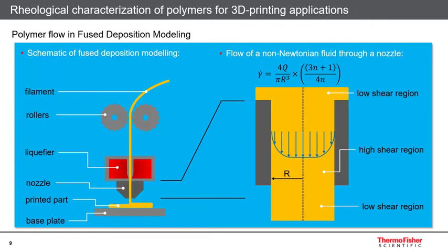If the viscosity is too high, it will be difficult for the printing device to create enough pressure to push the material into the nozzle and create a continuous stream at the exit of the nozzle. If the viscosity is too low, on the other hand, the material will flow way too fast through the nozzle and no precise dosing is possible anymore. The correct viscosity of the sample at a given shear condition is usually adjusted by nozzle temperature.